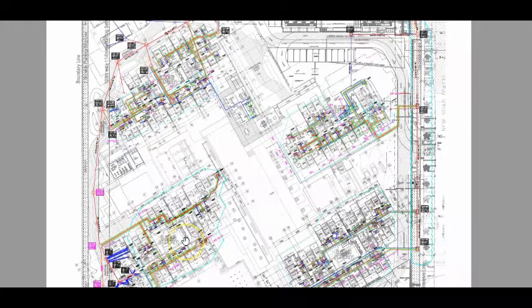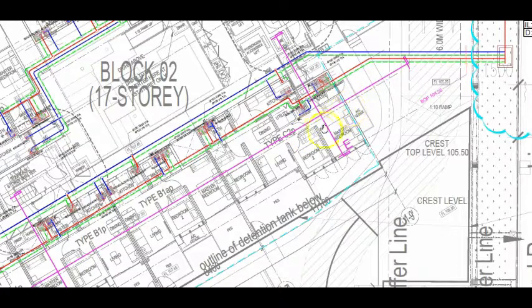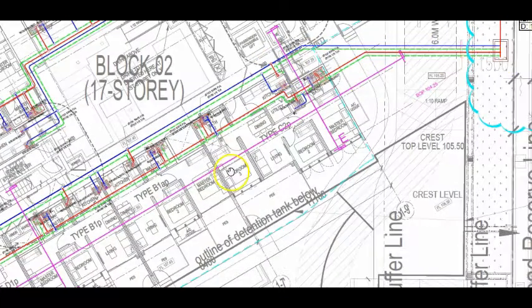Let's zoom down to the sanitary piping for one of the blocks. This is one of the blocks. As you can see, the branches from the riser or direct from the ground combine to the sanitary main, and need to maintain a gradient of 1:90 as per the code towards the IC. At the lowest point here, you need to meet the driveway headroom of 2.8.